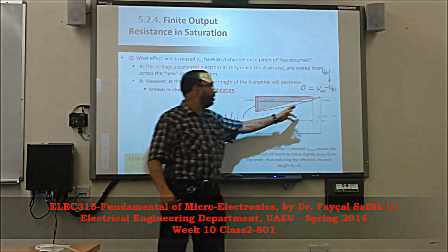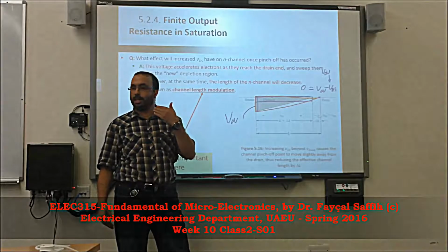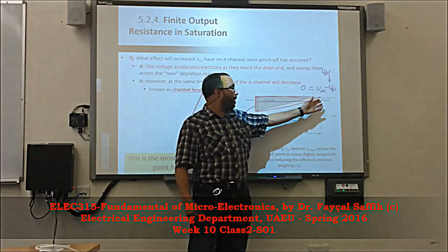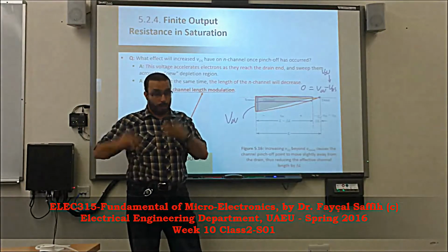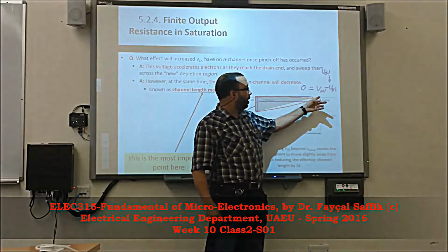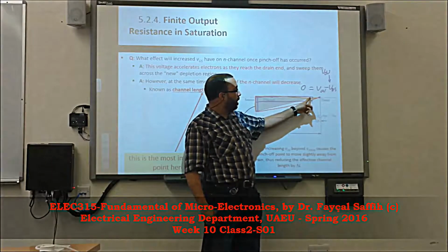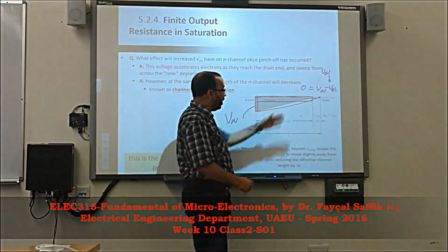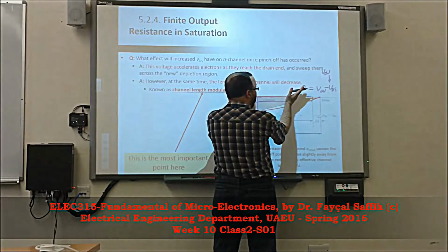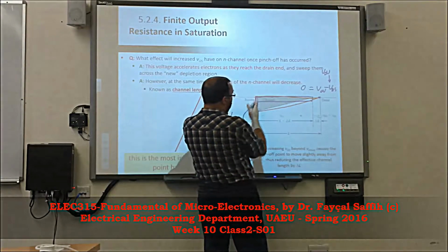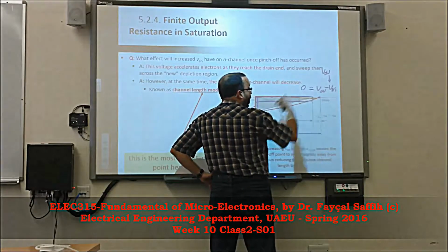And that's basically the definition of the pinch off. Now there is no charge for the channel here. That's what we said before. We just keep going. As we keep increasing VDS, we are going even further inside the saturation. Now the voltage here becomes negative, negative, negative, and the 0 will be here. So the channel pinch off point will move back to the source, because this voltage is kicking the pinch off point to the left.